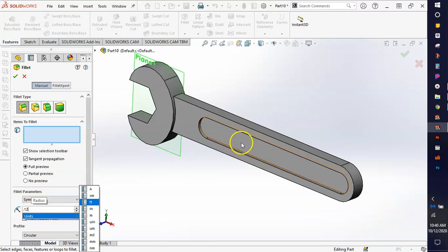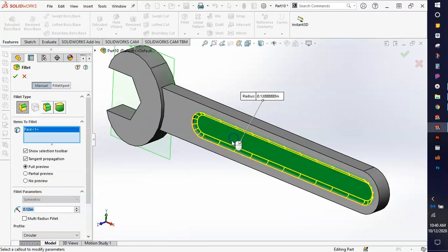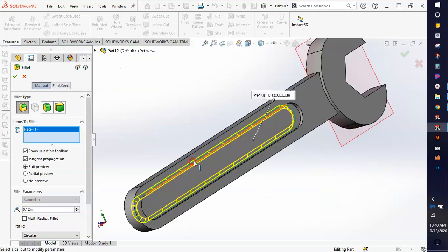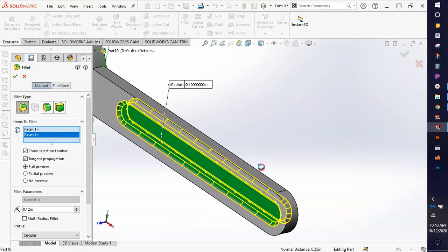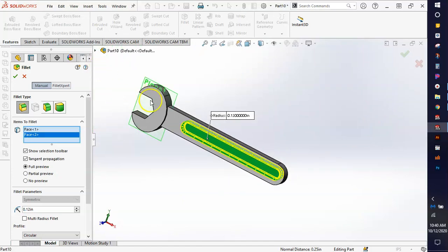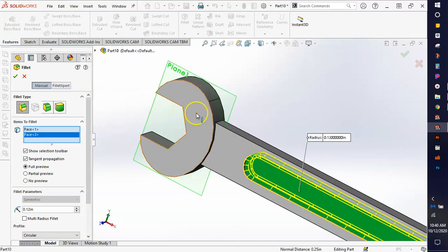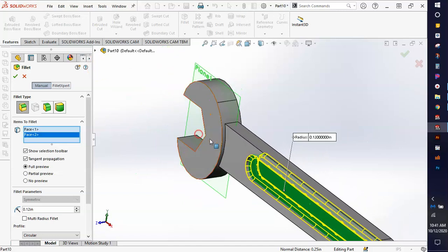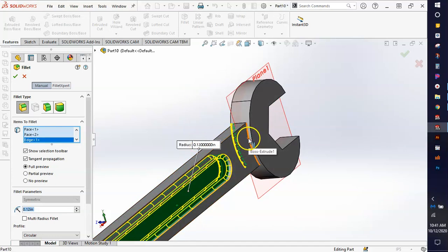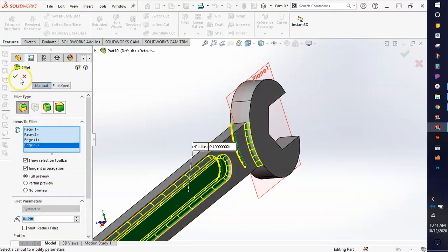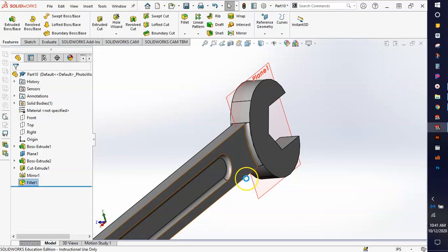And if you just click on the inside there, it should wrap it all the way around, rotate around, and we can do that side as well. And let's see if there's any others, say 0.12. There are. It says that this inside curve is 0.12, so we can select right there. If I rotate around, select right here as well, and we can hit the green check.